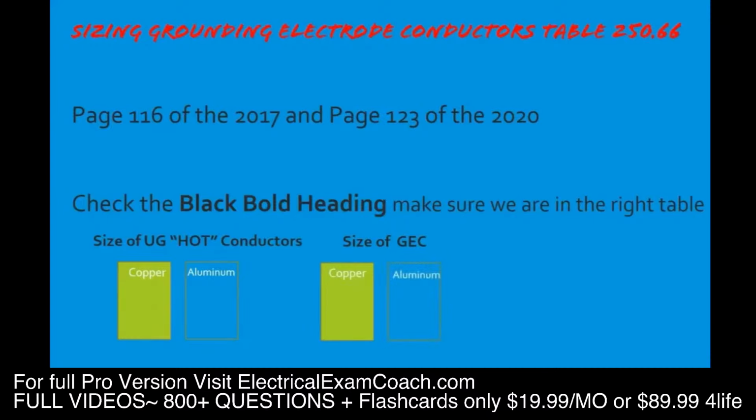Let me be very clear and very slow right here. If our mains are made of copper, we select from the copper side. If our mains are aluminum, we select from the aluminum side. Then there's a second conductor involved. It's the actual GEC itself. And we have to cross over and make sure we select from the right column, whether copper or aluminum. Because it's very easy to go copper and then want to go straight over to copper. But whatever your real world scenario or whatever your question states, you have to be very diligent to select from the respective column here and then jump over and select from the proper column here. But we're going to do a bunch of practice questions, and you'll be a pro by the end of it.